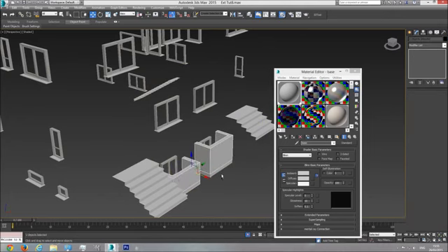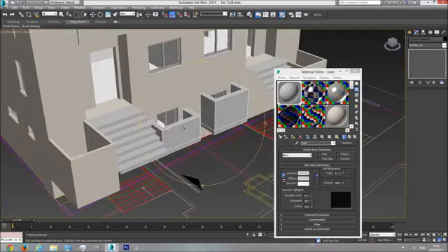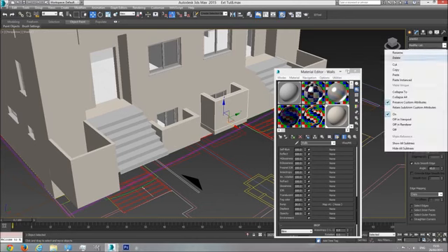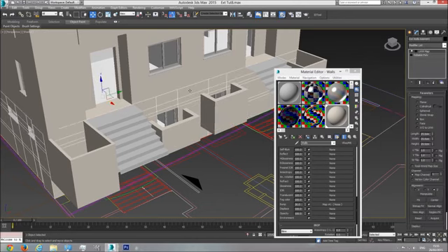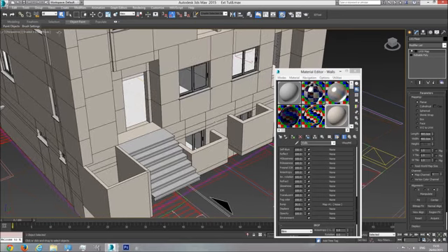1, 2, 3, and 4. These boxes, if I unisolate everything, are these ones here. They are inside the ground and they are the same texture as the building. So I selected the 4 of them. Walls, assign material to selected, and again I'm going to add, but I need to copy the UVW map from the wall again, because the UVW map I'm using now is from the floor, so it's not the same UVW map. F4 to see a wireframe.